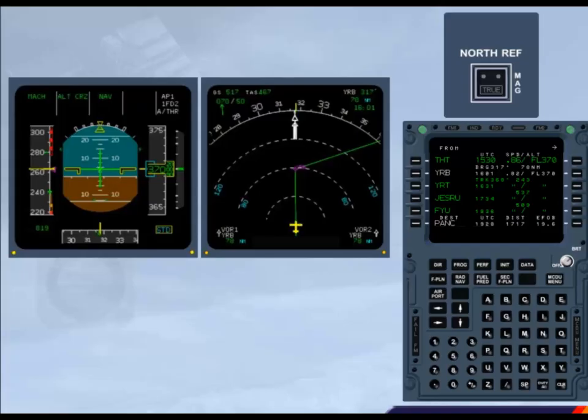At high latitude, or when entering the North Magnetic Polar region, the ADRUs replace magnetic heading by true heading on EFIS and DDRMI. When approaching the polar region, the ADRU triggers a message on the MCDU and ND requesting to change the north reference. Set the north reference push-button switch to true.